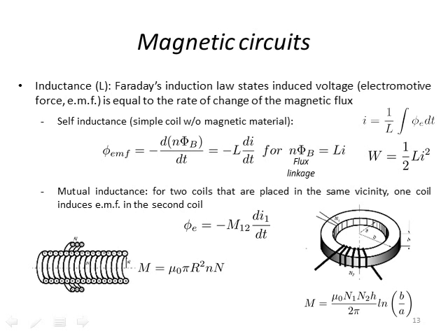And these are two examples of using this mutual inductance. We have two coils, one outside the other coil, and then inside the mutual inductance is going to be this cross-sectional area, and then the multiplication of the two turns, N for the inner and capital N for the outer.